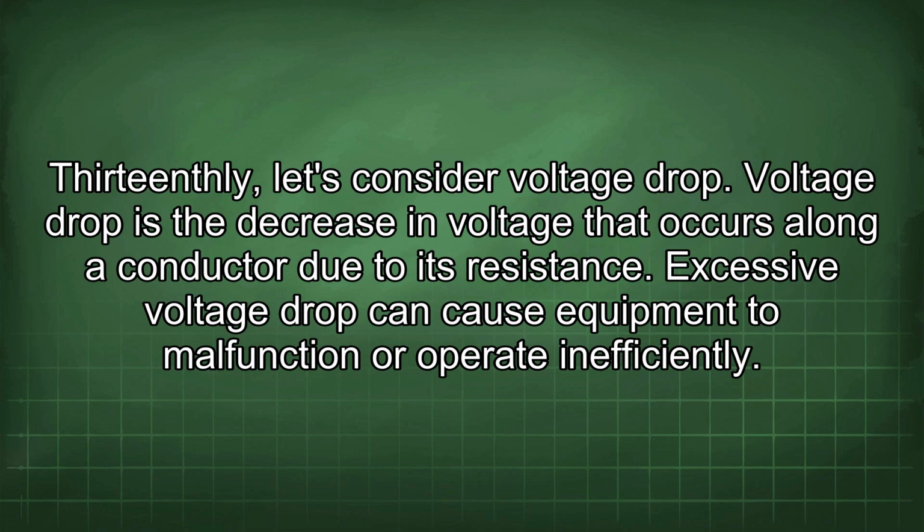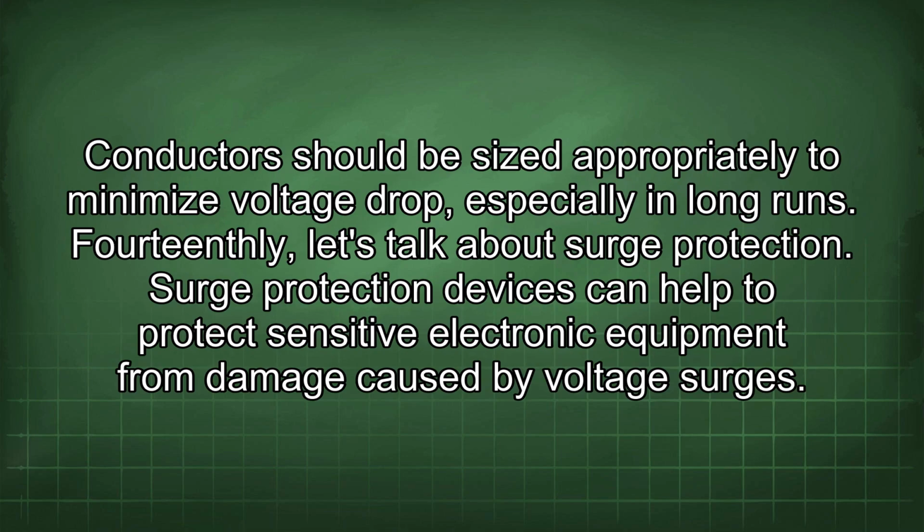13thly, let's consider voltage drop. Voltage drop is the decrease in voltage that occurs along a conductor due to its resistance. Excessive voltage drop can cause equipment to malfunction or operate inefficiently. Conductors should be sized appropriately to minimize voltage drop, especially in long runs.